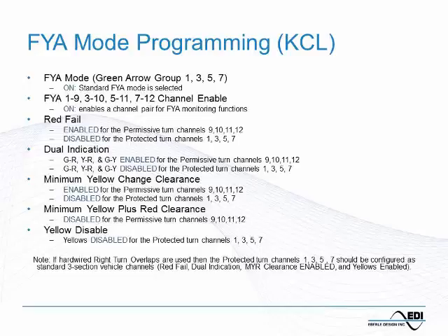In the case of the protected turn sequence, we go from channel 9 red to channel 1 green. Then to clear channel 1, we would go back to channel 9 solid yellow and then to channel 9 red. So pretty straightforward. Again, no clever I/O mapping, but it does require the installation of an aux file.